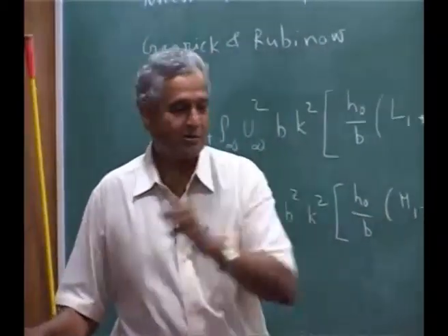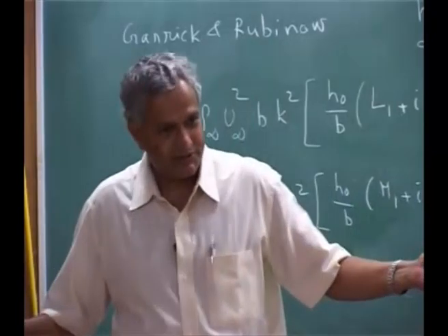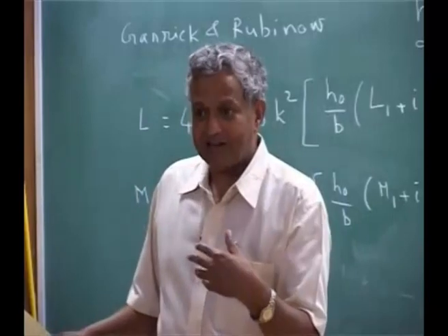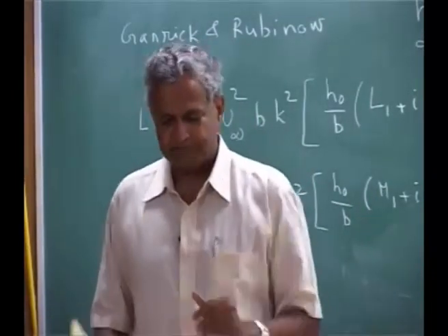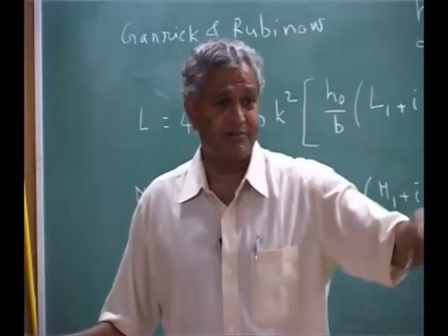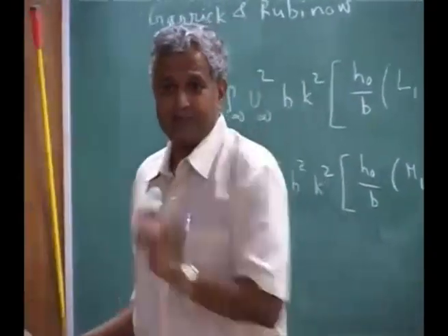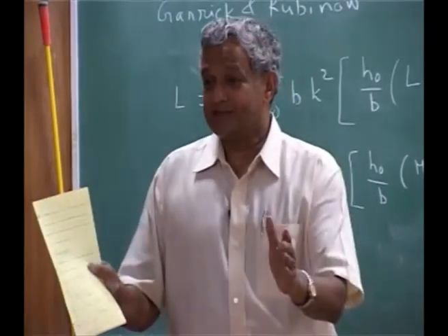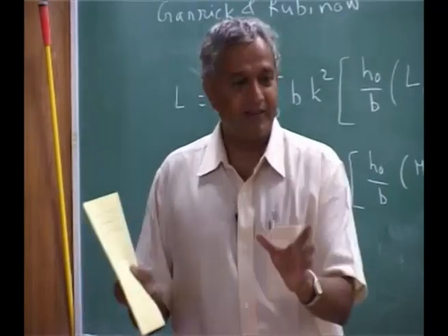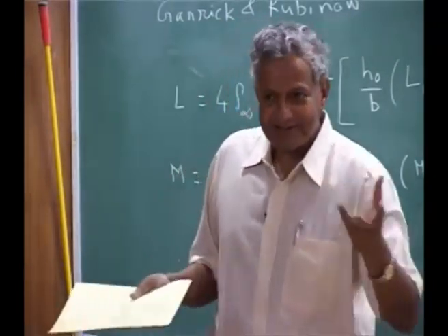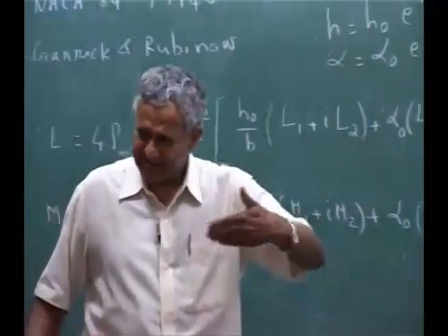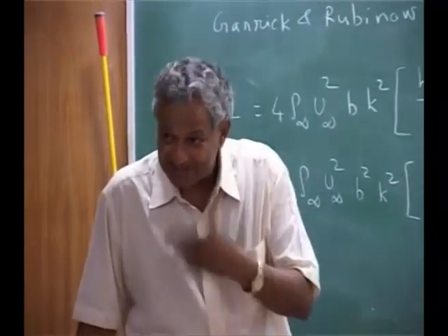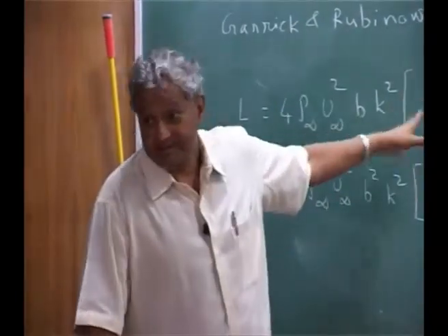That is like an input output, like a control system. Later we will bring the control theory into this to see how we have modeled the unsteady aerodynamics in the subsonic case. Input is motion of the airfoil, output is lift. Now this is like a control system, and you can always find a phase difference, and that phase is essentially responsible for all your various types of flutter problems. That is why the flutter analysis itself is done using this theory.